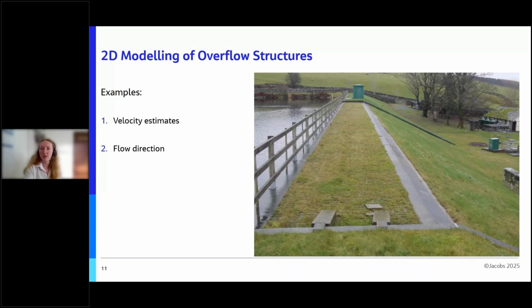Many reservoirs are designed with a wide section of the embankment lowered to act as an overflow, as shown on the slide here. I don't know if you can see, but this section here is a bit lower than the ground here and here. The overflow is designed to come online in high magnitude storm events and send flows over the dam crest and down the downstream face.